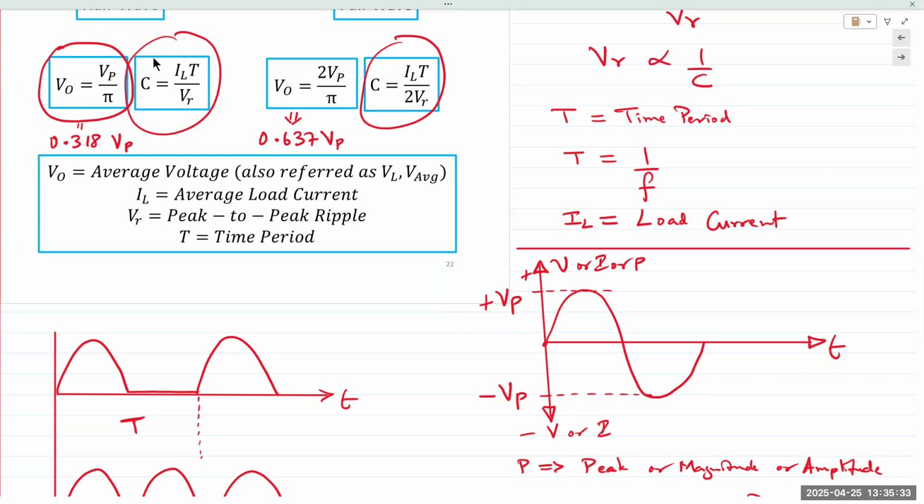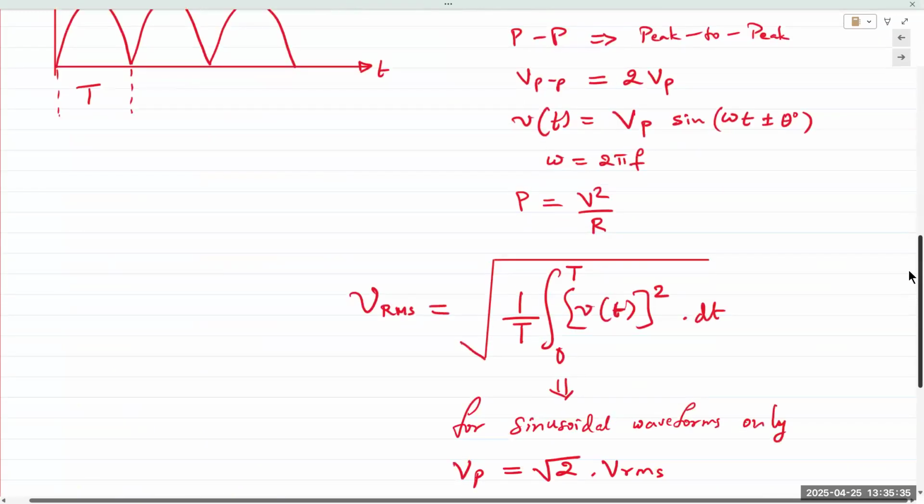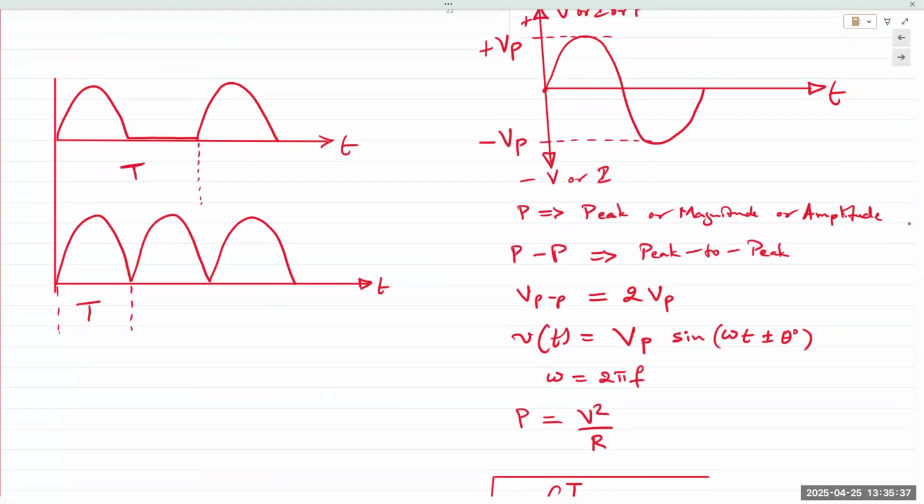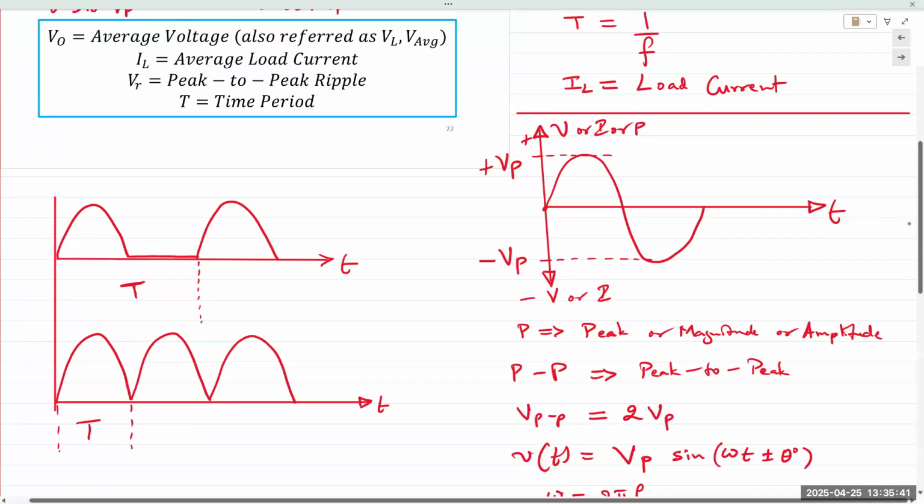It's doubled because the negative half cycle is also being rectified. So it would not be the same. That was my point. The frequency would be different, so you'd be averaging it out over one cycle versus two for a sine wave.